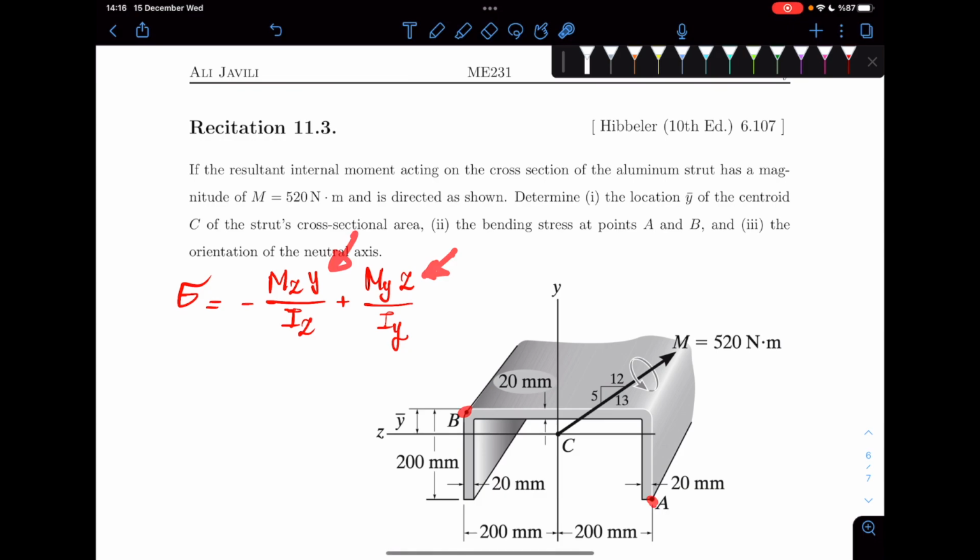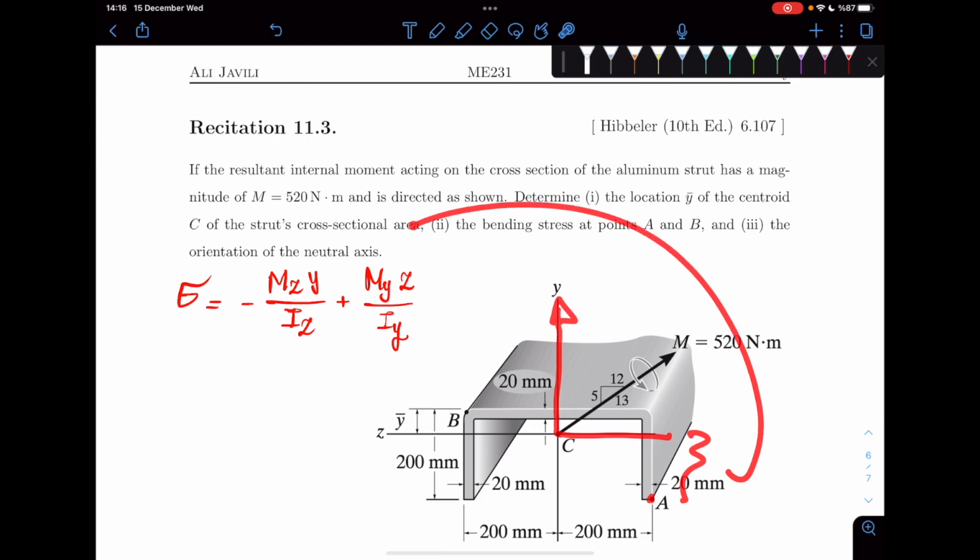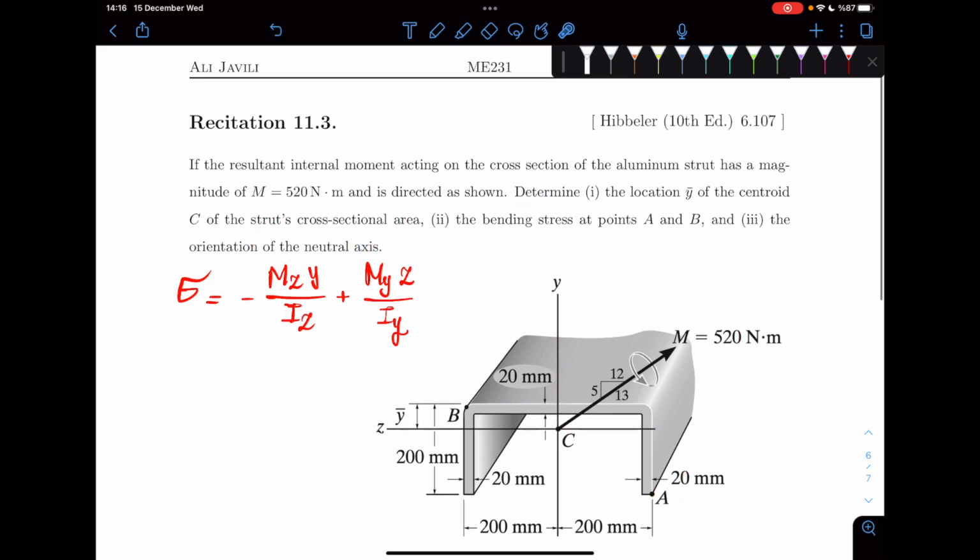So for instance, after you find out your centroid, you should remember that the axis y is upwards. So when you want to calculate, for instance, the distance for point A, here you would have a -2, okay? And then, okay, there's another minus and they cancel each other and so on. That's one thing that you need to be very careful about.